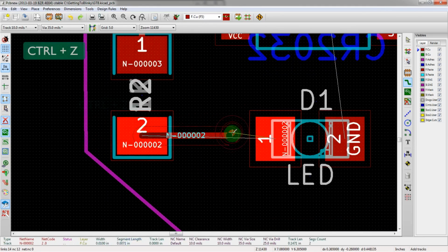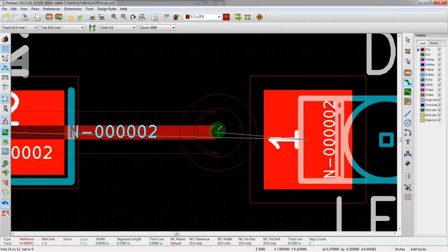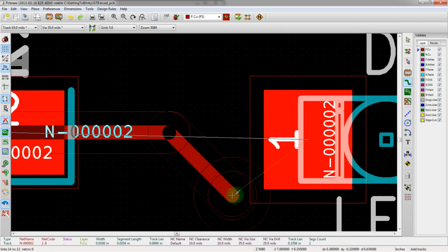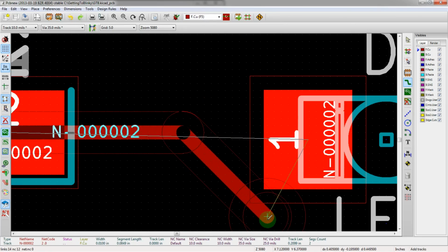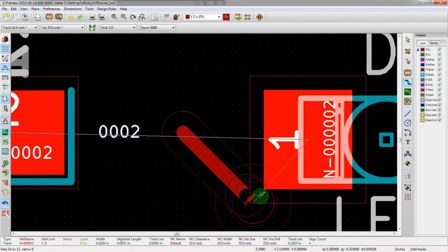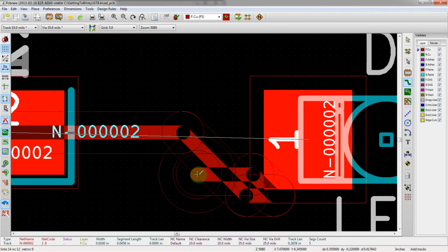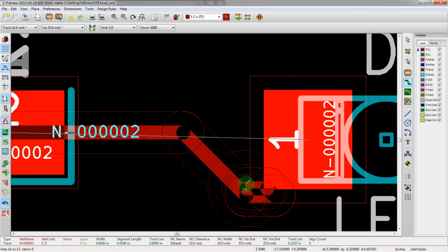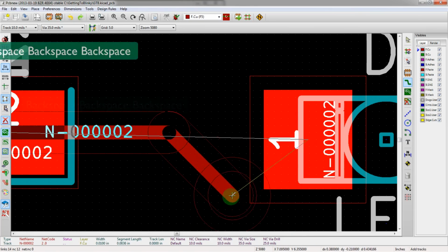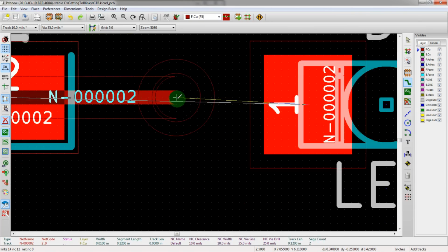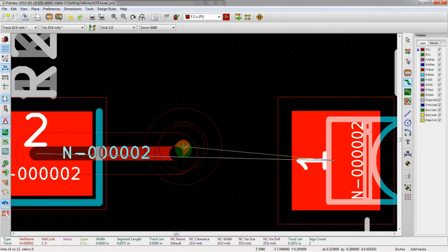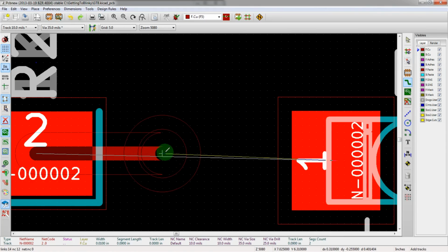You can see as I click and draw that there's thinner lines on the outside, and what those are is actually clearance lines, so that if you cross a thin line with a pad or another trace, it will not let you draw it that close. You can click, it's actually not going to let you draw it though. And that's a great feature because, especially as you start getting more components on board, you might want to make sure that you're not running into problems. We'll actually do a check later with DRC, where the design rules checking shows the spacing that we want.